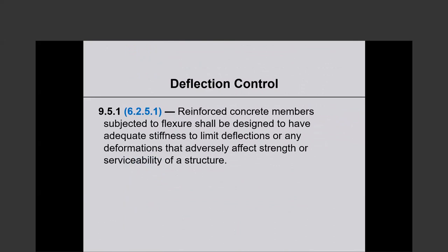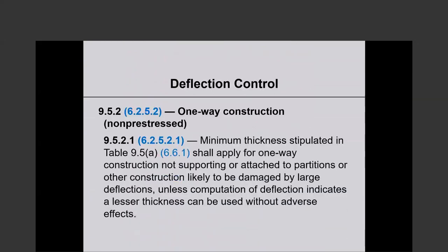In design, all of those things come in. Analysis is analysis, find me strength, but design involves all of these aspects. So reinforced concrete members subject to flexure shall be designed to have adequate stiffness to limit deflections or any deformations that adversely affect the strength or serviceability of a structure. Okay, deflection control in ACI 318.